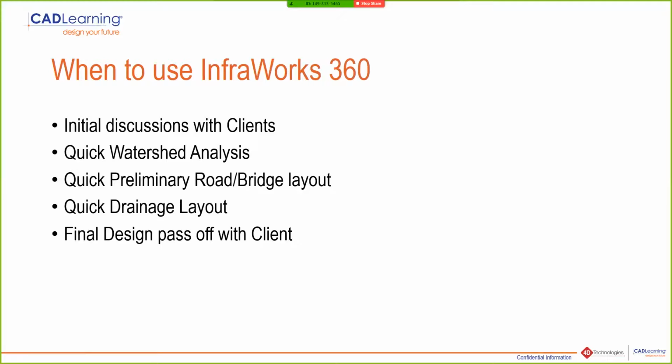You can quickly lay out roads. And when you lay out a road, if it's going to cross something in the terrain like a channel or a stream or a river, it will automatically insert a bridge along the road, of which you can go back and change how the bridge looks, whether it's steel or concrete. You can change up the piles and the footings and the foundations, and you can send that bridge information off to AutoCAD structural for analysis, and to Revit. So it will do both roadway and bridge layout, from simple roads to massive interstates.